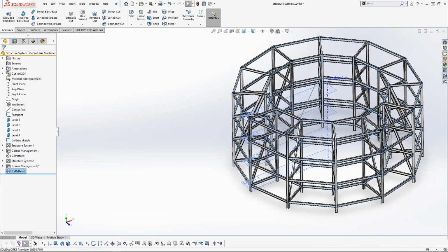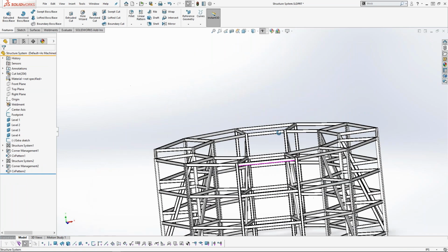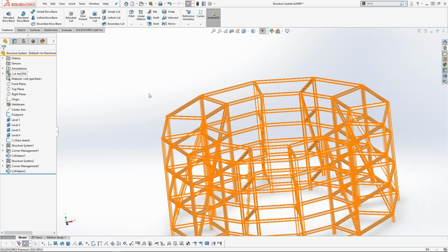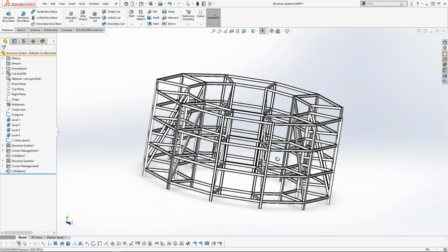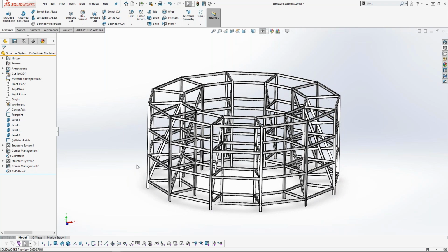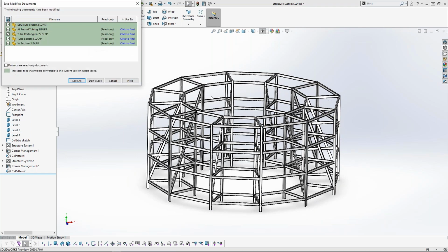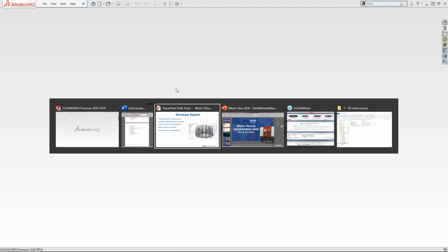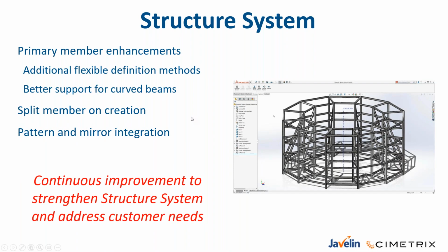And very quickly, we're able to create a very complicated welded assembly with a complete cut list of 204 bodies in just a couple of minutes. So no reliance on weldment groups, no reliance on sketch segments here. We just use points and planes in order to define all of our weldment geometry. So again, more improvements to this tool. It was new in 2019. So, a lot of feedback came in from the SOLIDWORKS community about what they wanted to see inside of this tool. And there were some really nice enhancements to it in 2020.